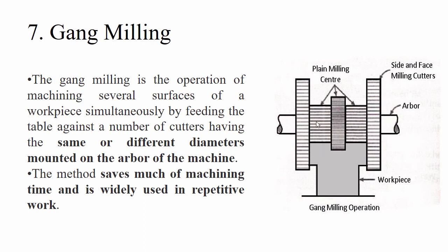So again you have to bring the tool, again you have to cut here, right? So again if you want to cut, one more action has to be performed to remove the material at the center. So gang milling makes sure you save most of the time unnecessarily wasted during the clamping and unclamping of the tool and workpiece, in most applications. This is about gang milling, right?